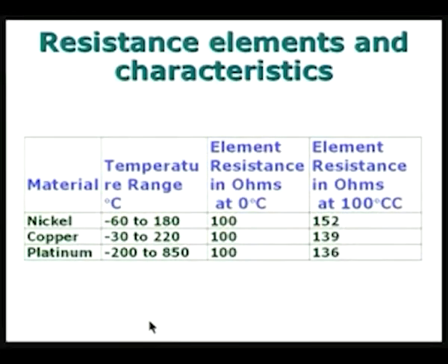If there is a definite one-to-one relationship between temperature and the resistance, it can be used as a thermometric property, and the resistance thermometer can be used as an instrument to measure the temperature. So, the resistance thermometry depends on the unique relation that exists between resistance of an element and the temperature. And let us look at some of the resistance elements which are used in practice.